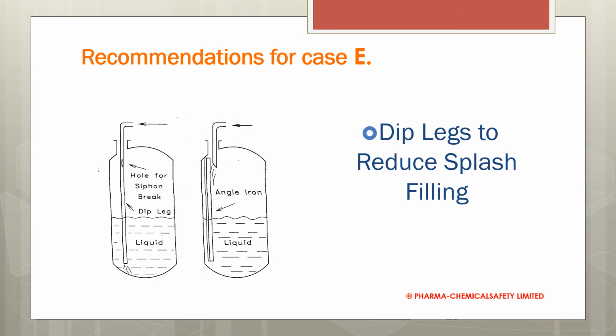Use dip legs to reduce the splash filling phenomenon. So you need to design your reactor in the same way. You have an agitator, which may be difficult, but other recommendations, like following NFPA 30 for the maximum flow rate, can help.